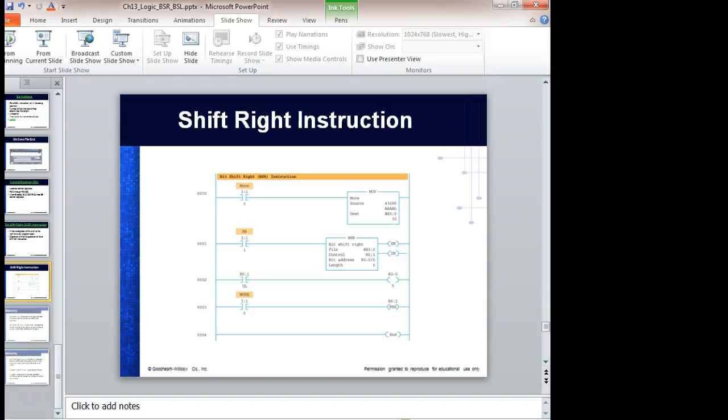So right now the control register for this bit shift right is R6:1. Once you assign this word, then we do element addressing. We don't have to know the bit numbers because the bits have names. So the UL is the unload, the DN would be the done. After it shifts that 7 times, the done bit would go